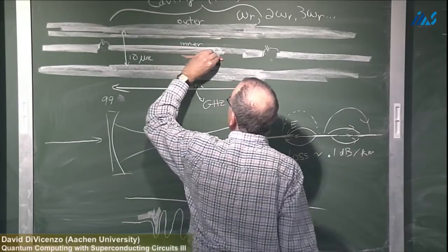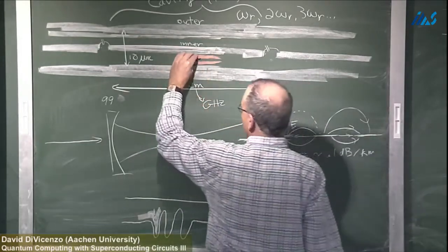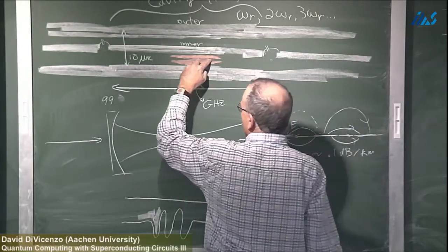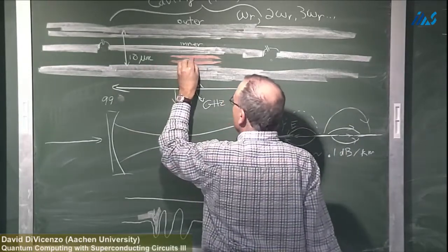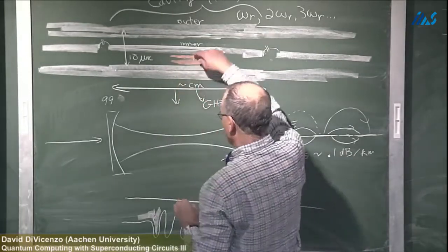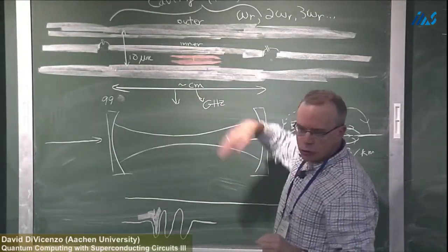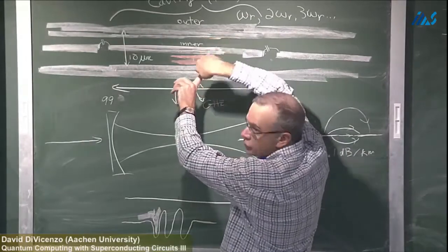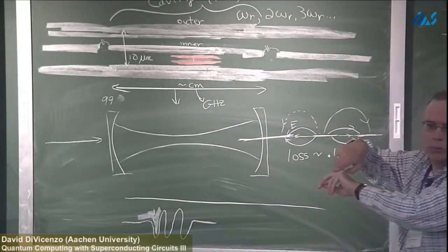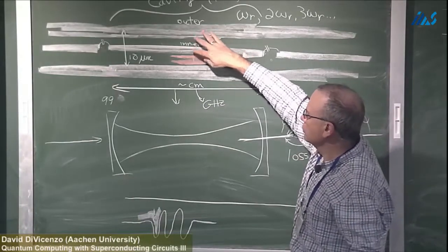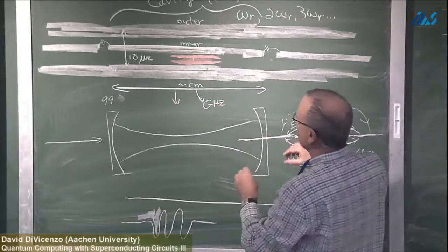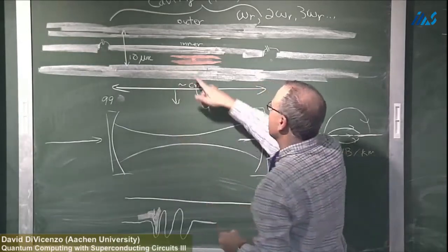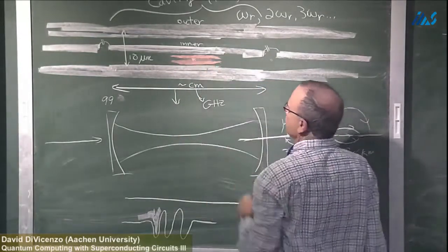And so what mostly is present is capacitor. Remember, I've emphasized the transmon is made to have a pretty big capacitance. And then in here, which you really can't see, is some very, very tiny bridge between these two pieces of pink metal. It's all aluminum. And then in here is some crossing thing, some Josephson junction. So that's really on some completely invisible scale. Of course, I'm using some false scales anyway. I can put an X in here just as a reminder that, yes, there is, in fact, a Josephson junction there. But mostly there's capacitance here.